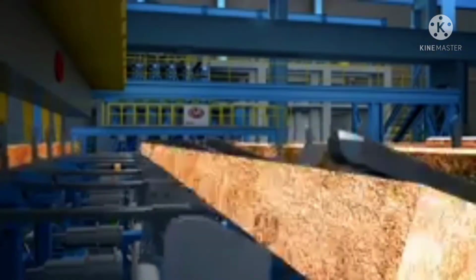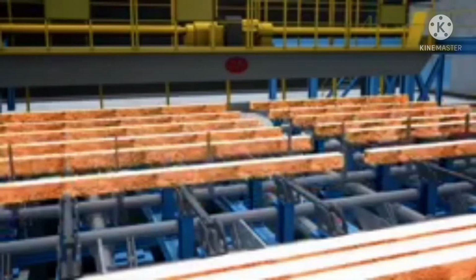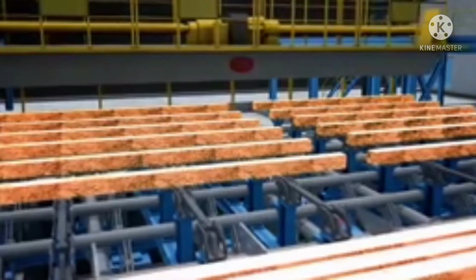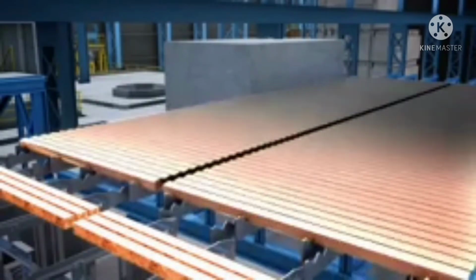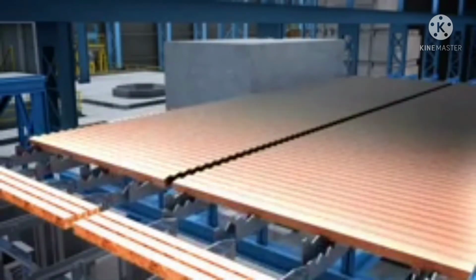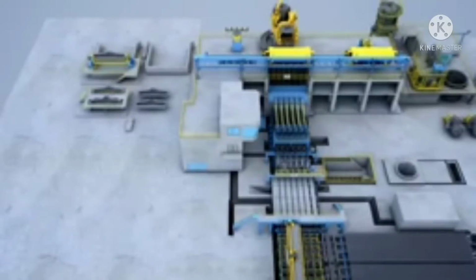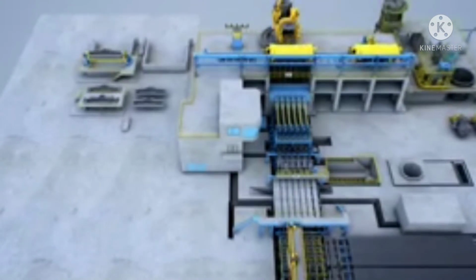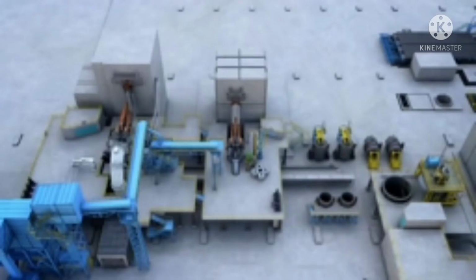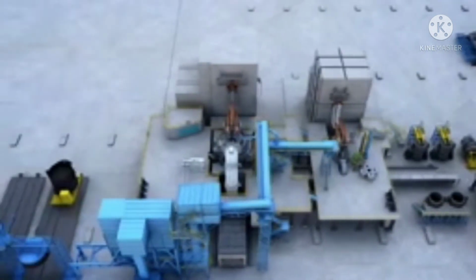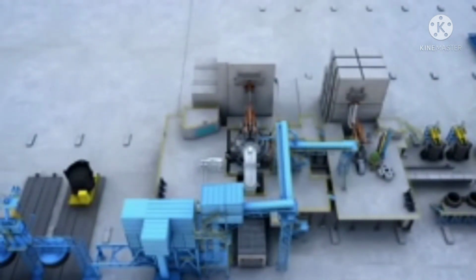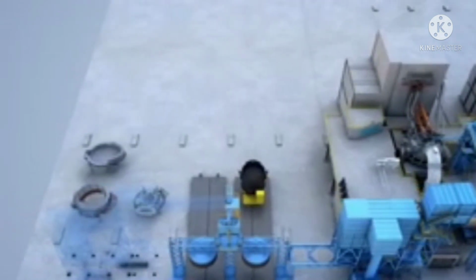Also known as primary forming, the initial shapes of slabs, blooms, and billets are formed into their various shapes, usually by hot rolling. Products that are hot rolled are then divided into flat products, long products, seamless tubes, and special products for one last stage of processing. Finally, a variety of secondary forming techniques including shaping, machining, joining, and coating gives the products their details, shapes, and properties.